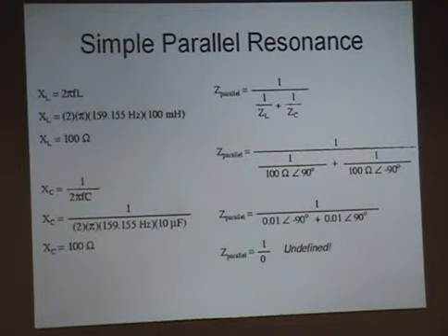This is what you're doing when you're loading your antenna, when you're taking your MFJ tuner and all of a sudden tuning it. Look at the difference in power of just a few hertz difference. What we're doing, in effect, when we're tuning is we're changing the reactance of the system, not changing the frequency. But the same thing happens. All of a sudden, all your power goes to the antenna instead of burning up in the feed line or burning up on inside of your radio.